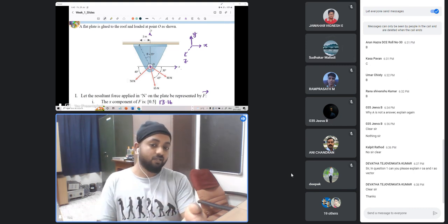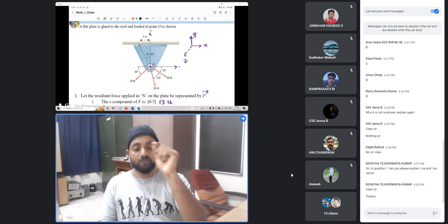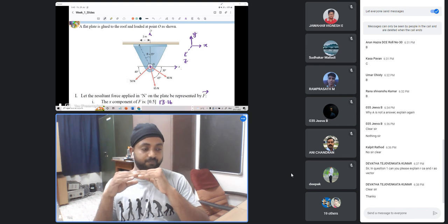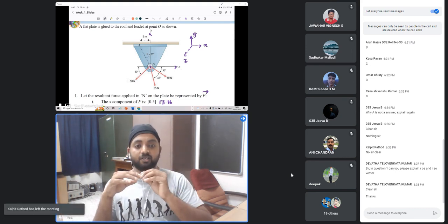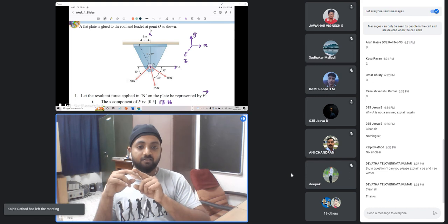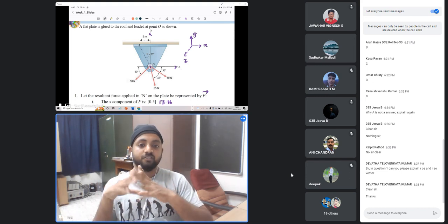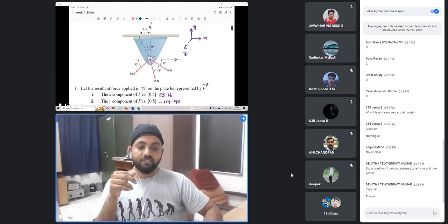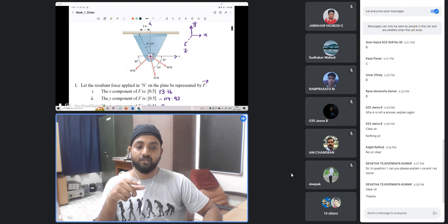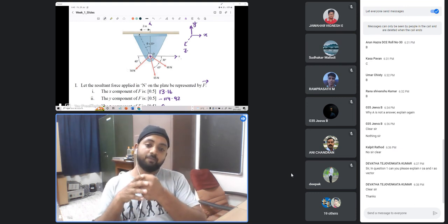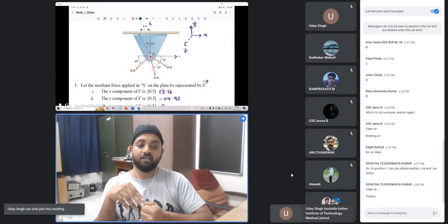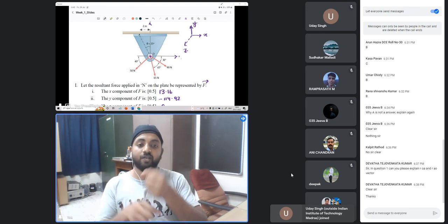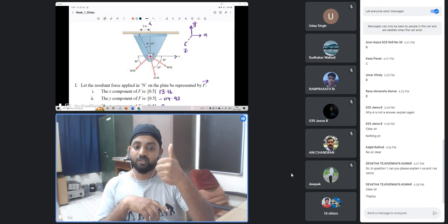So the third question that we asked, if this were to be represented by an equivalent force and moment at A, let us say A is at the surface, and we are drawing the free body. Now we have to transfer all this to A. We will have one force which will have to balance out the downward motion. If we see here, Fy is minus 114.92. So the force applied at O, the plate is being pulled down by 114.92. But we can actually see that it doesn't move. So the top surface, the roof, has to apply an equal 114.92 to counter this force.